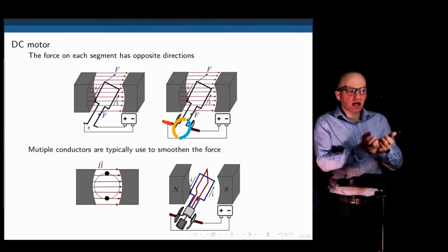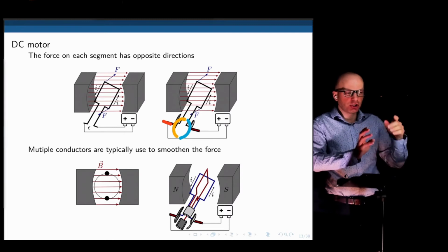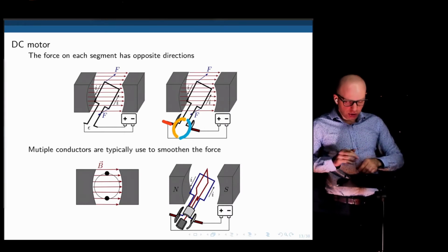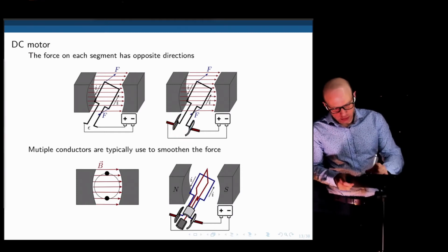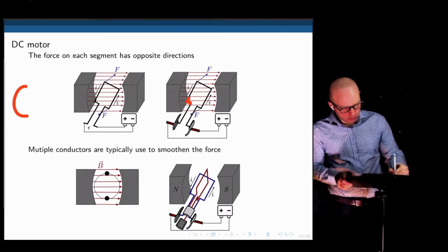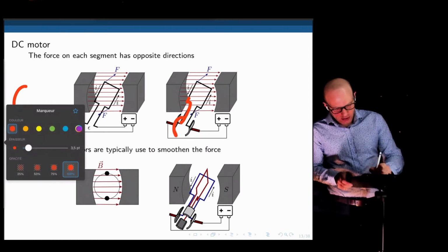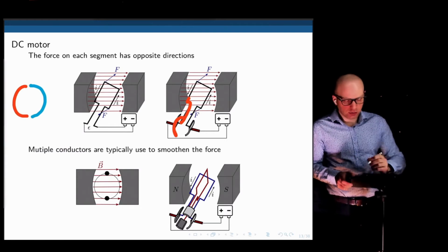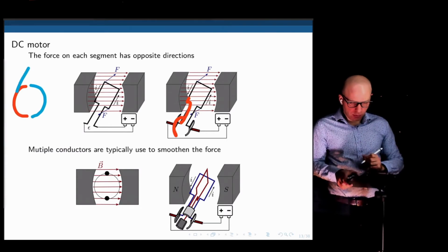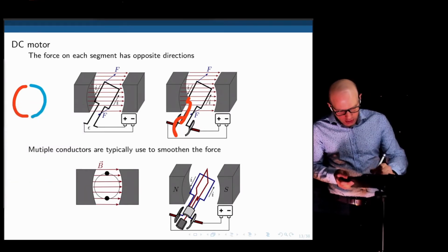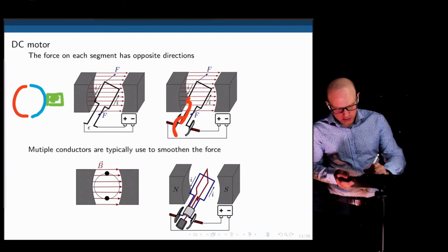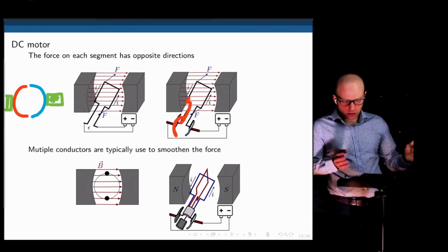The motor itself inside has a mechanical connection that will ensure that it changes polarity. Let me try to explain this one more time, because it seems like it's not very clear. So let's say this is one side of the coil, this coil here. So you have one commutator, and here we have another side of the coil. Right, so both go to the coil like that. And they are rings, they are metallic rings. And then you have these parts that are pushing against the rings, and they are connected to a DC source, for example.